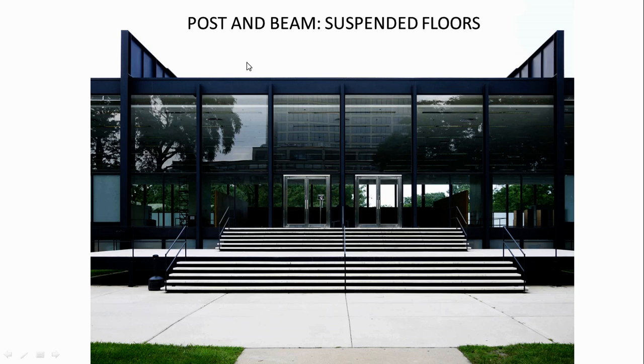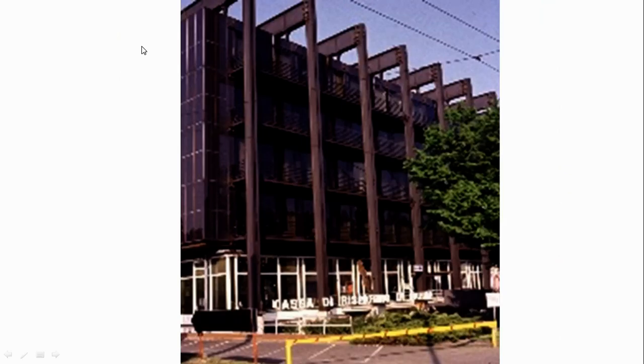That's a big girder, isn't it? It's a solid web with a little bit of reinforcing for that part there. And there we go again, same idea. The floors are being hung from a series of goalposts. As I say, I like this because it's a very clear understanding of the structural logic of the building. These are a series of bridges in pure compression. The floors are hung from these bridges.